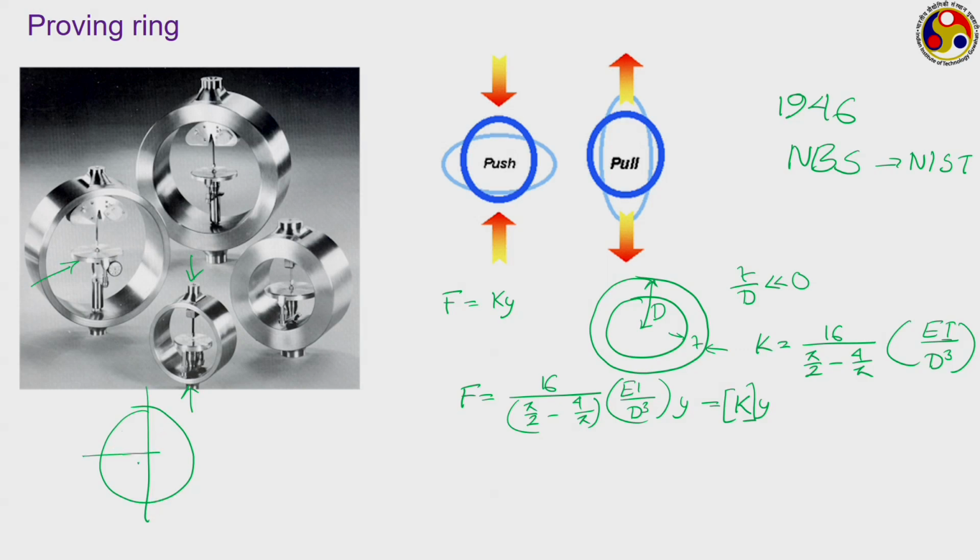Now, if there is a deflection of this one and the deflection is measured in terms of an angle phi, then the corresponding bending moment can be related as M is equal to PR by 2 into (cos phi minus 2 upon pi), where R is the radius of this particular circle, initial radius, P is the, oh sorry I have written both to be R, it should be P. P is the pressure that is acting on this, and M is the corresponding bending moment.